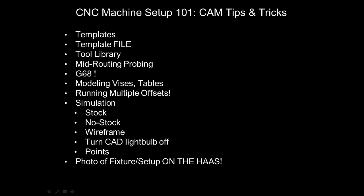So with the Renishaw probe and a Haas G68 command, and I believe the other controllers have this as well, it will actually update my whole coordinate system, or it'll rotate the whole coordinate system to compensate. So the extreme example is you could basically never tram your vise in, have your vise at a 4-degree angle, and it'll still make square parts. I don't encourage this, certainly at that degree, but for doing minor amounts of tweaking, it's phenomenal.